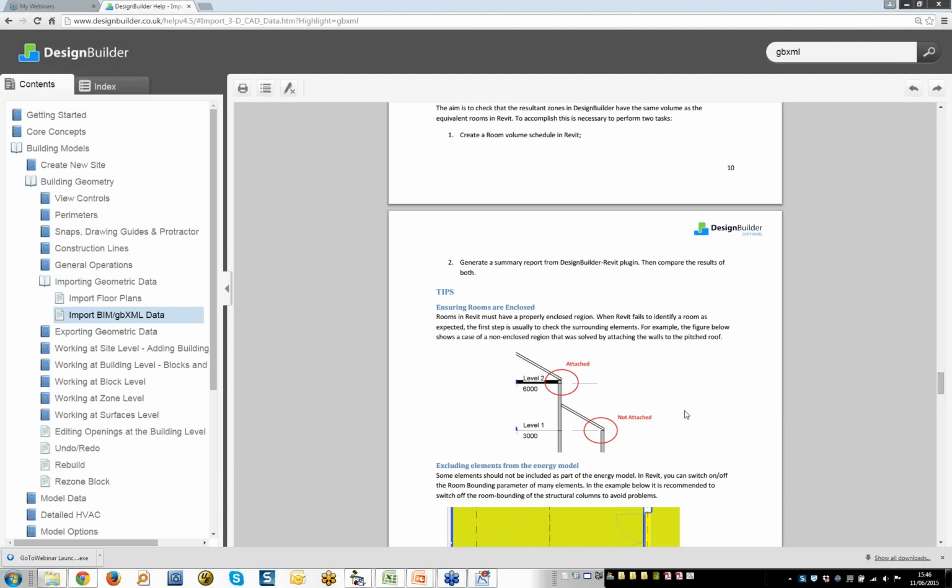There's a question about 2D and 3D thermal bridging effects. I think part of the Energy Plus ground model introduces a 3D ground conduction mechanism. I don't think that Energy Plus per se has a 3D thermal bridging effect, but DesignBuilder certainly has linear thermal bridging in place in version 4, but no 3D bridging.